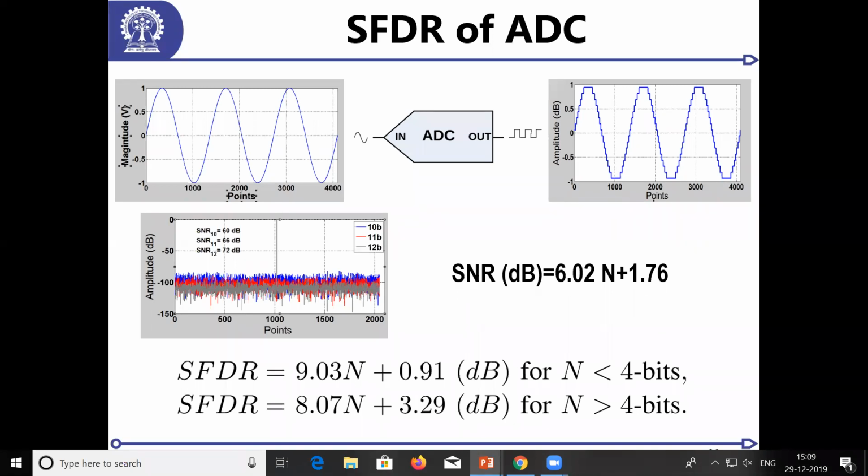Now I want to find out: can I digitize 0.1 volts? If I apply 0.1 volts, what will be the output of the ADC? The ADC is just one comparator which has 0.5 volts as the threshold, and the other input is the Vin. What will I get? 0.